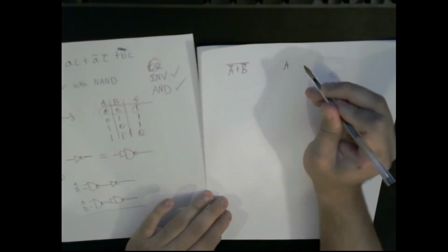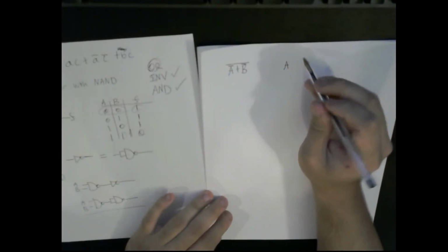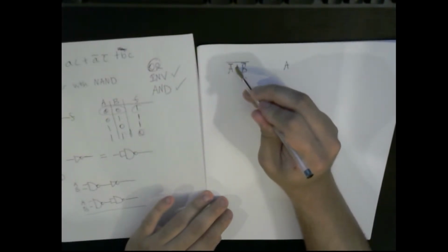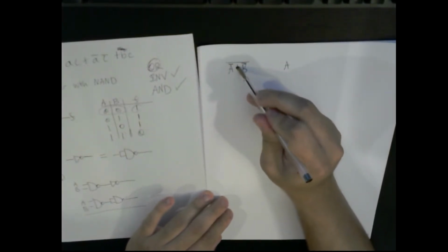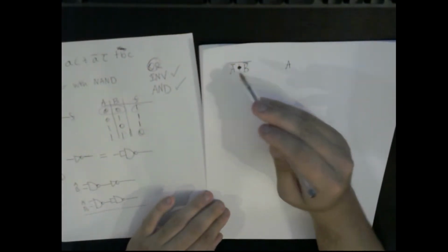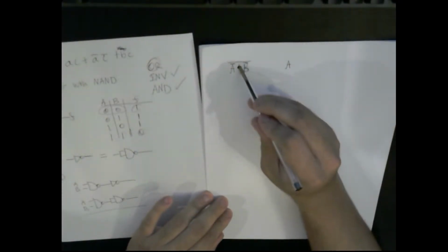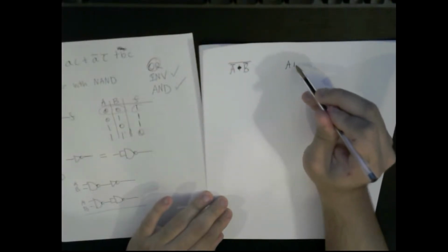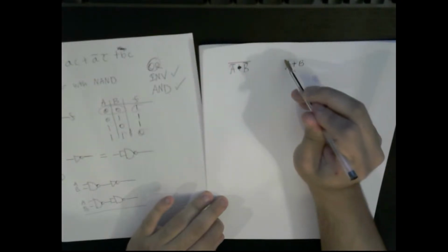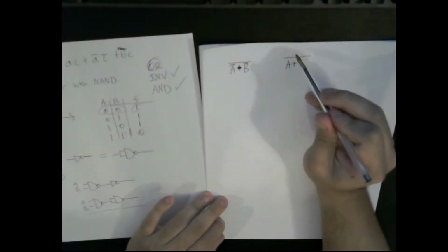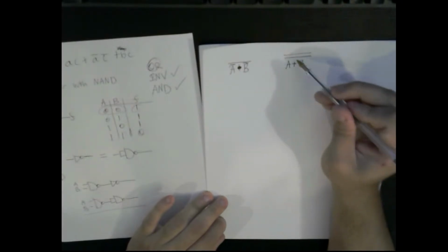I get A, I messed up here. This is an AND, right? This is not multiplication. I mean, this is not a plus sign, this is an AND. What I can do is combine the line and change the sign here. Sorry if I confused anyone about that. So this AND is going to change to an OR, and these both have inverted inputs, so that goes to a line. I combine them, but these cancel out, so I get A plus B, which is an OR, which is what I want.